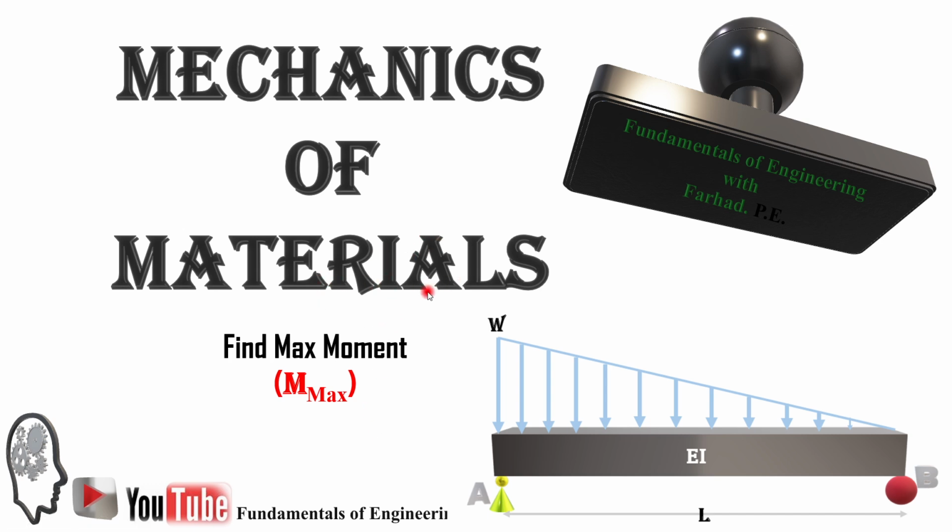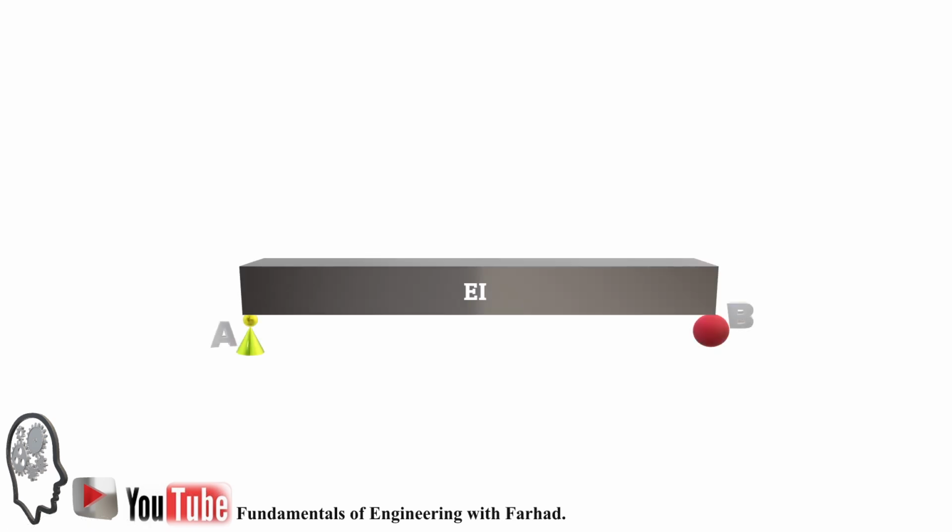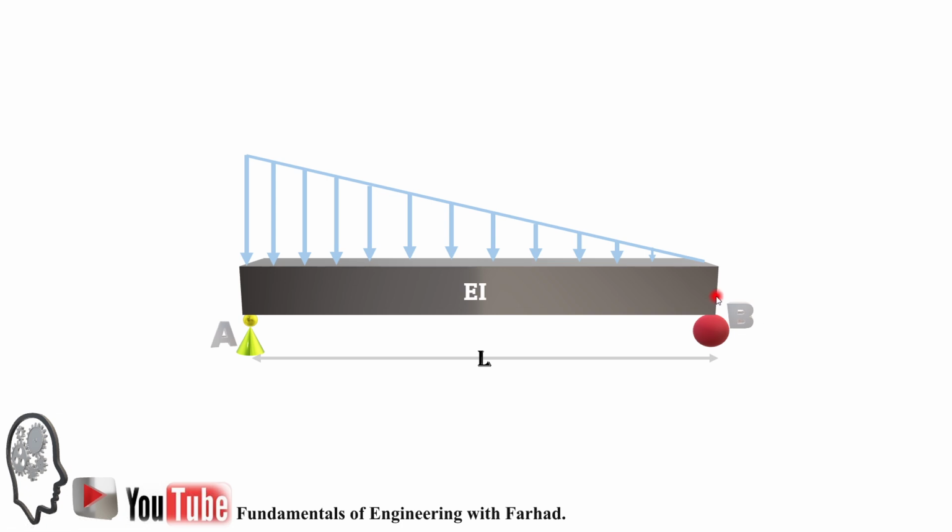Materials. We are about to go through a very interesting example in finding the maximum moment in a beam, a simple support beam with a triangular loading. So in this example, we have a simple support beam AB with the distributed loading which starts from 0 at one end and goes all the way to the maximum intensity of W in the other end. This is a triangular loading on a simple support beam. We want to calculate the maximum moment in this configuration.